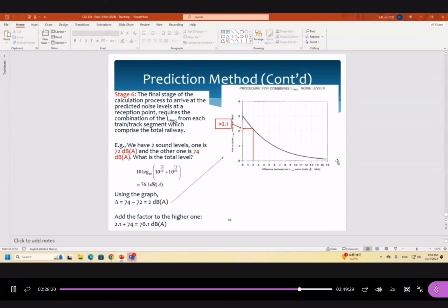For the noise control, in the coming two tutorials, I will have some relevant questions for you, so that at that time, you may have a better understanding of how to make use of these documents for petitions, okay? In this lesson, my target is just to share with you the basic principles. And remember, all the correction factors here are expressed in terms of dBA, okay? Not dB, dBA. We can only make use of dBA for environmental noise assessments, okay?